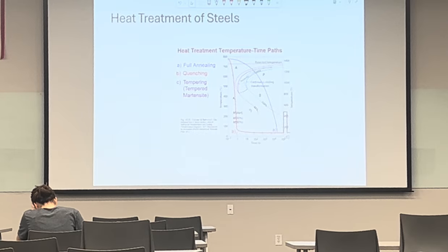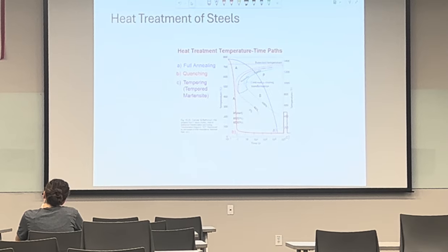If you keep reading into the chapter, they mention the three factors to expect, or I should say, the successful heat treating of steels to produce those martensitic microstructures throughout the cross section is going to depend on the composition, the type and character of the quenching medium, and the size and shape of the specimen. And then in there they mentioned hardenability and things like that. I don't think we're going to need that for this next question.